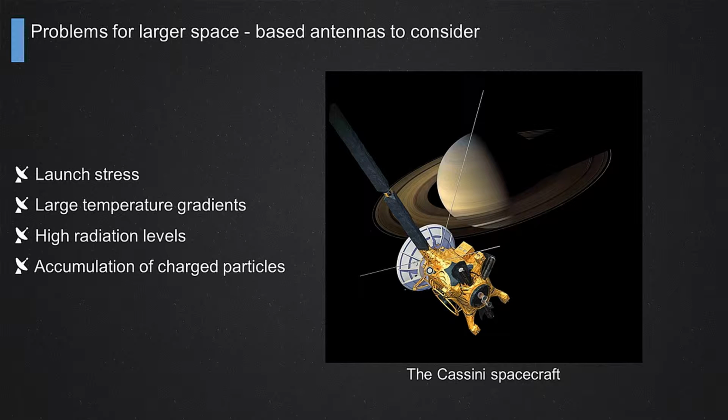So this is a good reason why antennas have to be grounded, to avoid that such large reflectors collect electrical charges and create problems in terms of discharge of this accumulation of electrostatic charges, creating problems to the rest of the spacecraft. So there are several problems associated to make such a big antenna able to reach the far sides of the solar system, working at different frequencies. And by the way, this antenna is guaranteeing the connection of the mission to ground, to the Earth, over the complete duration of the mission itself.